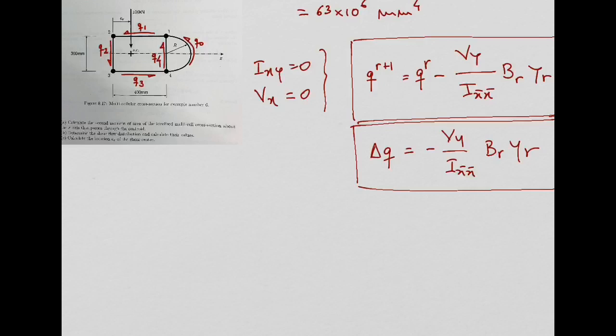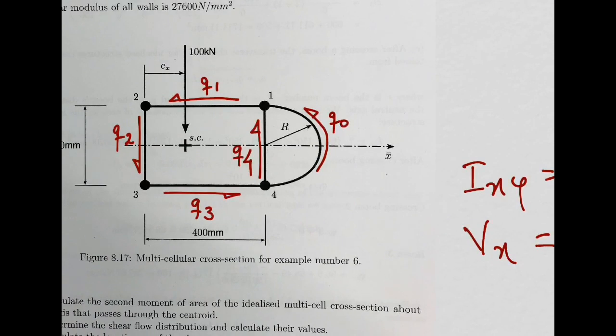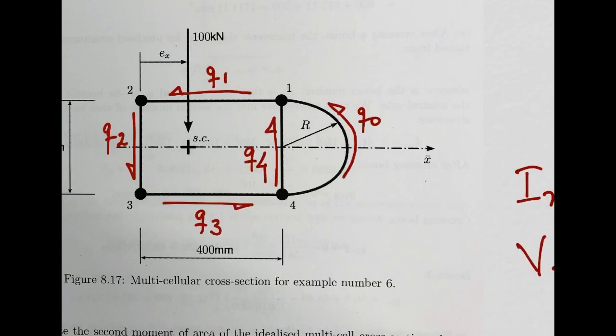So, for example, if we start crossing... Oh, there's one more thing. This is a two-cell cross-section, right? We have two cells here. And this is a closed cross-section. So we have that problem with the initial shear flow, remember, from previous weeks? So we need to assign for each cell a shear flow that we assume we know already, or is given, okay? So we need to do that for each cell.